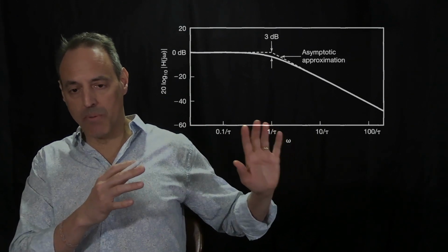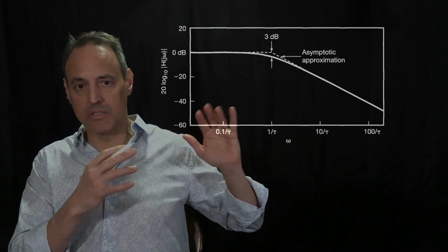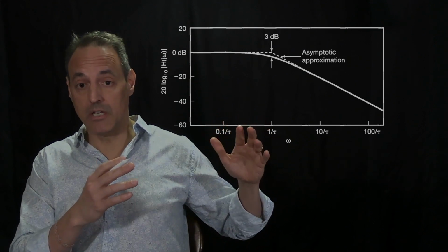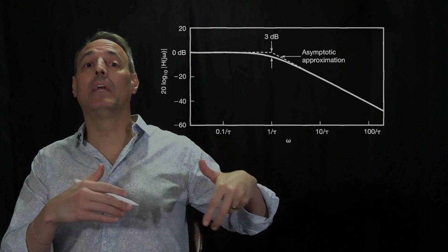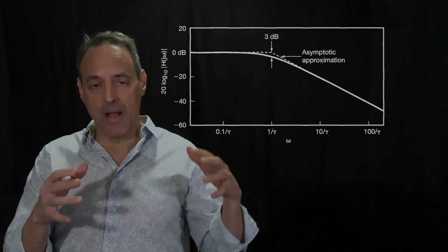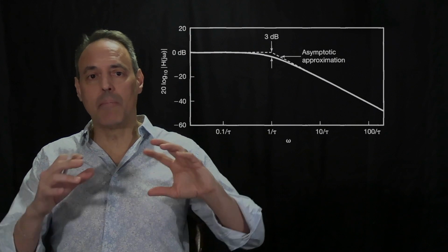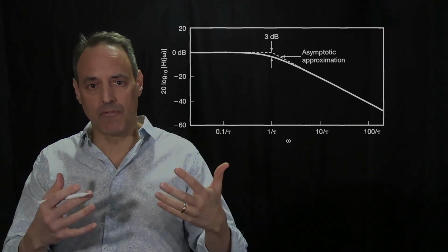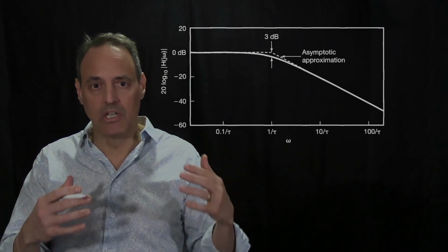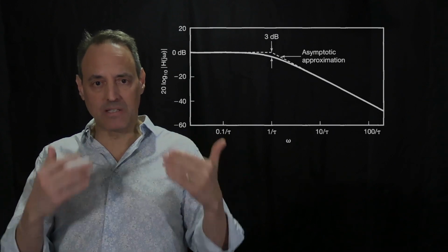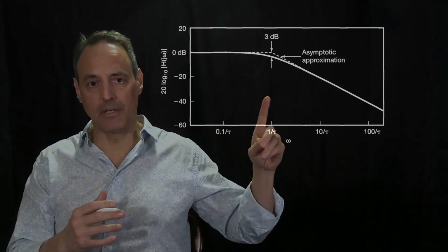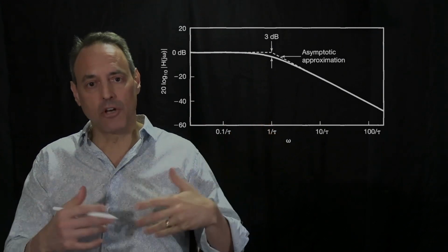And this Bode plot is super important because it's starting to characterize what the signal looks like overall. At least this is the intensity of the response H. The one last piece of the Bode plot is then to look at the phase response of the signal as well. So you get both the phase and the intensity. This whole chapter is about the time frequency, so really the amplitude and phase of what's going on in the Fourier domain is going to really matter for us in terms of manipulating signals. The last couple lectures I've shown you that if you also manipulate the phase of the signal, it not only can warp the signal, but it can move it in time. That, along with this filtering, which is exactly what you're seeing here, determines what's going to come out of your system.